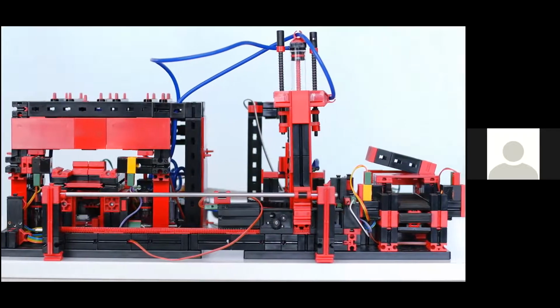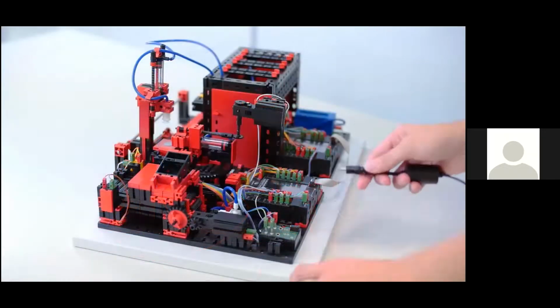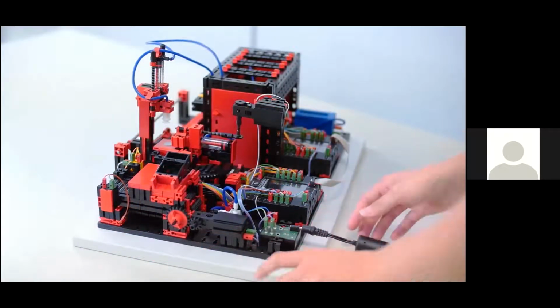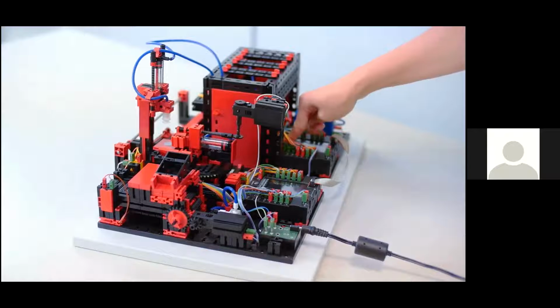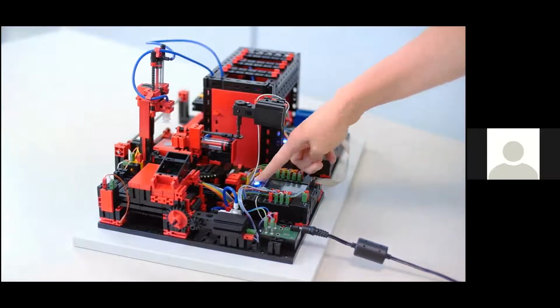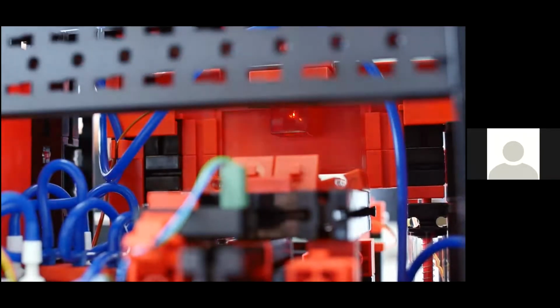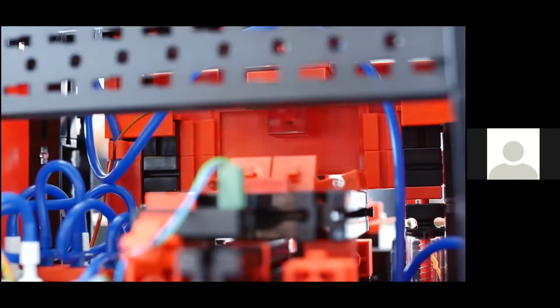Components used on this model include 4 mini motors, 6 push-button limit switches, 2 photo transistors, 2 LED light barriers, 4 solenoid valves, and a compressor. The dimensions for this model are approximately 20 by 14 by 12 inches, and it has a weight of around 11 pounds. Again, the standard version of this model is a 24-volt version for use with the PLC of your